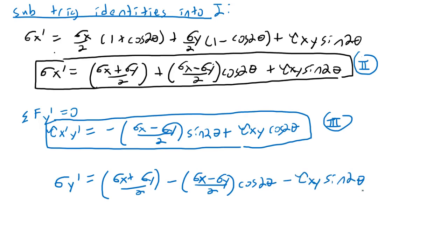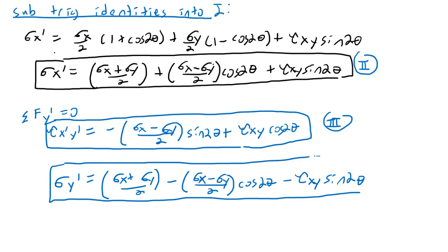And this is equation 9-3 in the book. Another one, and this will be another one of our critical equations to work with. So what we now have is 3 equations. Notice what we have. The inputs to these equations are, as a reminder, 9-1 in the book, 9-2, and 9-3. The inputs to these equations are the sigma x, sigma y, and tau xy in any coordinate system of your choosing.